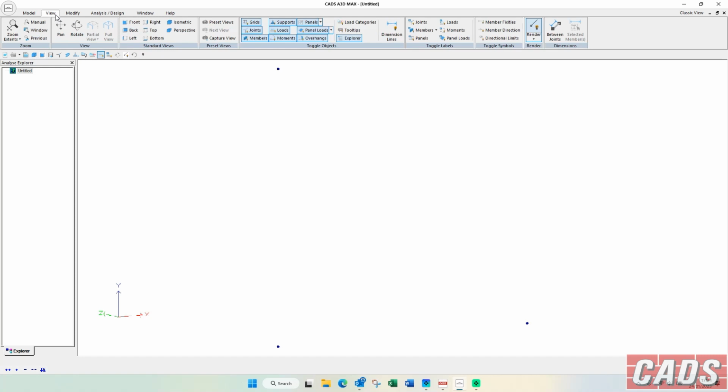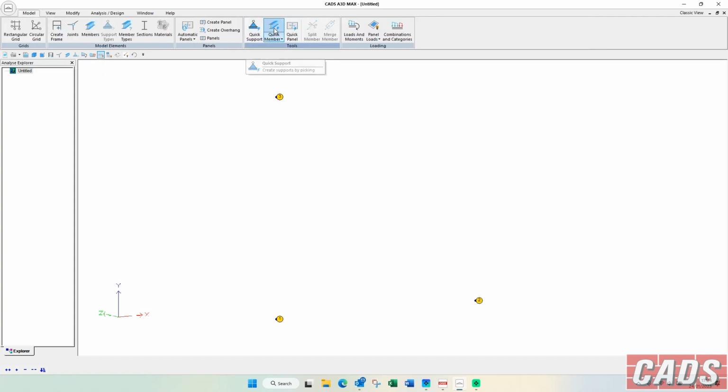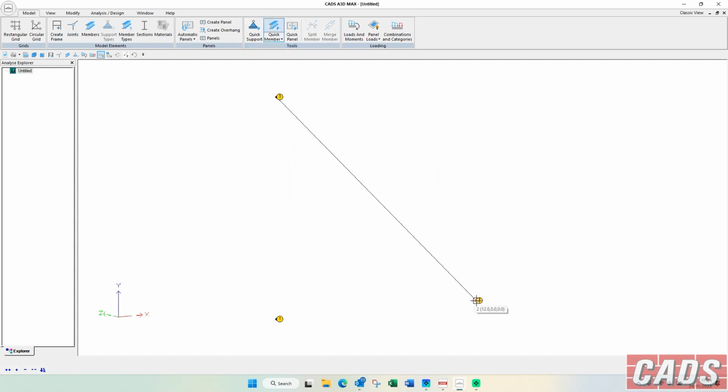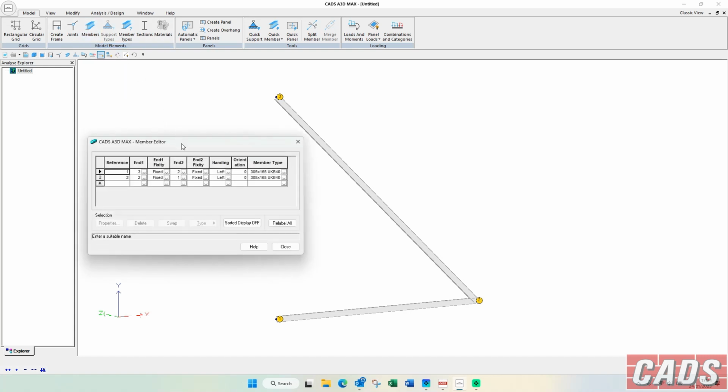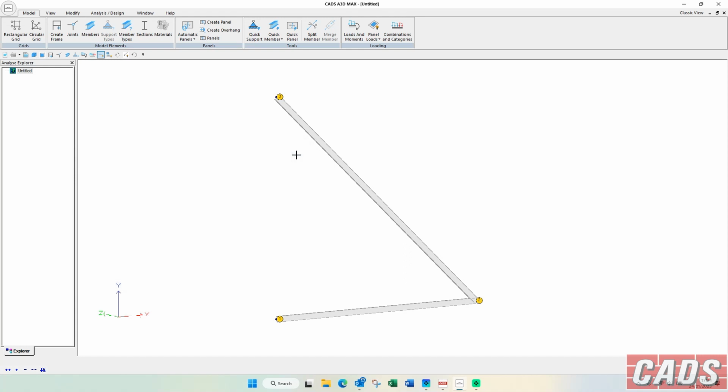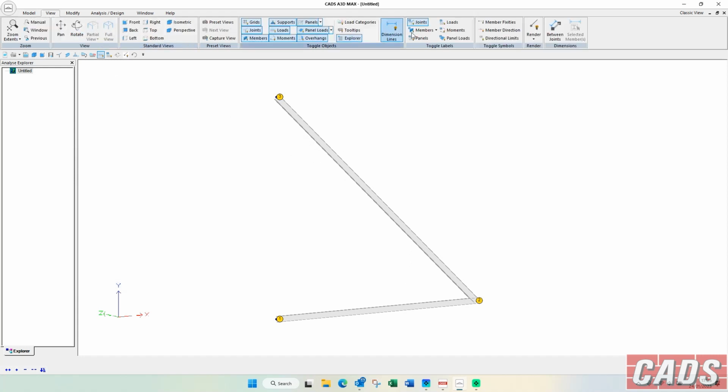And once we've got them on the screen, we can number them up just by clicking the joint button here. And then we can create the members by just using what we call quick member, choosing a section type, and literally joining up the dots. So from there to there, and from there to there. There we go. And then just end mode. You can see the rendering here. Now, obviously what's happened there is that node 1 has been connected to 2 and so on. That's actually gone straight into the little panel here. So you can see member 1 goes from 3 to 2 and so on and so forth. So that's the sort of thing you'd have to do in the past. Now it's done graphically. We can add the member numbers and the joint numbers there.